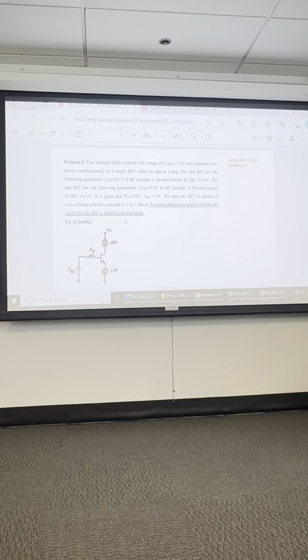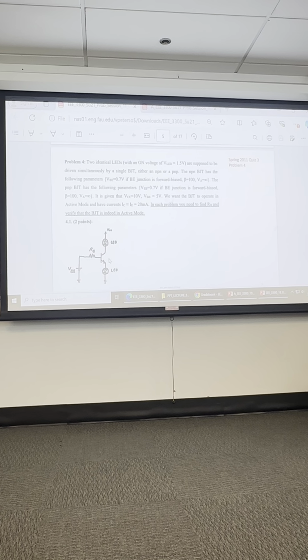The way we're looking at these problems is that you want to reduce the tendency to produce multiple results for a problem. When you get into multiple results, a 5-minute problem turns into a 15-minute problem because now you've got to investigate each one of those results. So before solving a problem with BJTs, study the circuit and come up with a logical method to work with it. That way you don't have to get into diodes which are on and off.